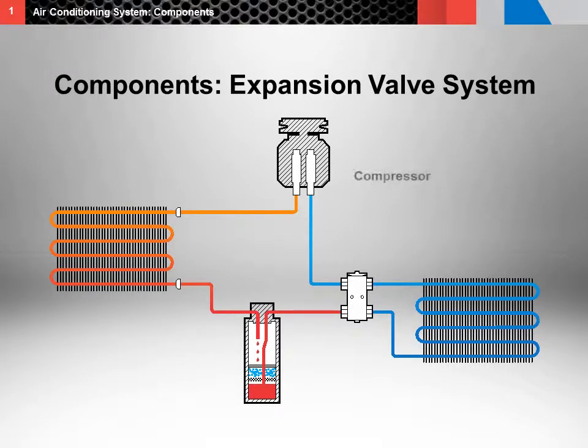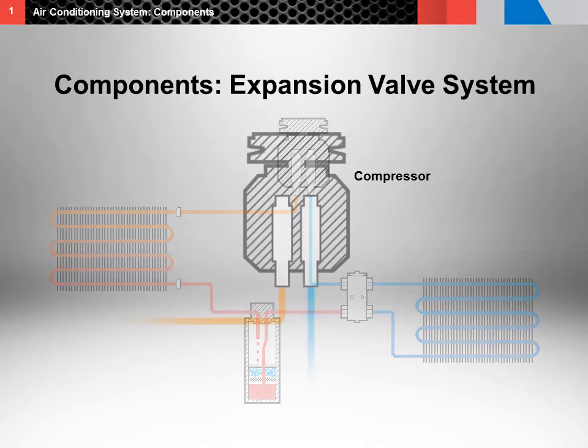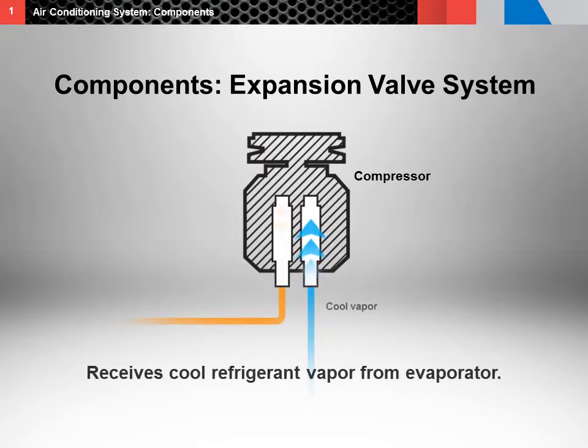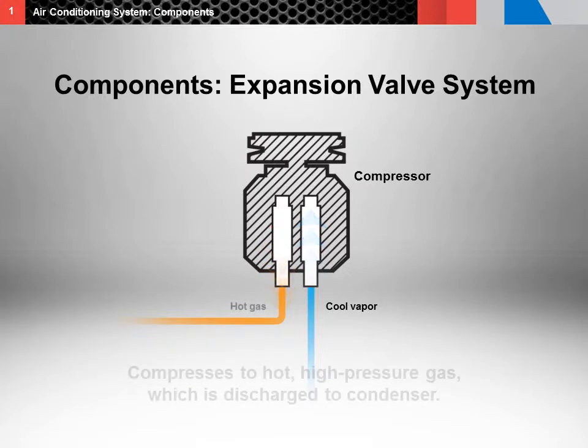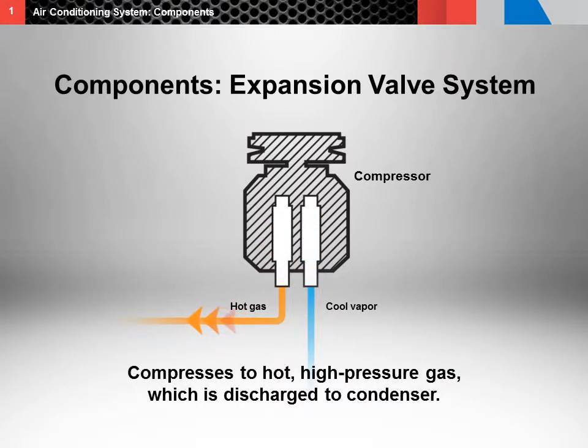One major component is the compressor. The compressor receives cool refrigerant vapor from the evaporator and compresses it to hot, high-pressure gas that is discharged to the condenser.